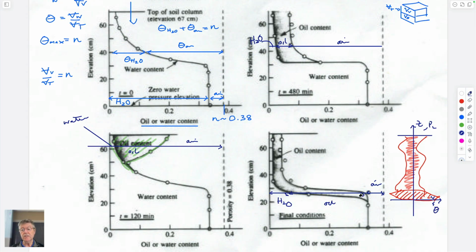This puddle that sits on top of the water table, it's buoyed by the water table. What it's done is the water table started off higher and it's pushed it down because it has the weight of a liquid sitting on it rather than just a gas on it before. So that weight of liquid is what's pushed it down here. And as the water table has been depressed, it's forced this puddle to sit on top of it. And that puddle exists at a pretty big percentage. It's probably taking up 80% of the void space just looking at this.